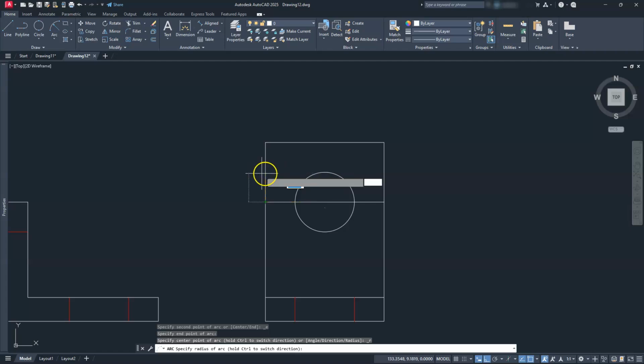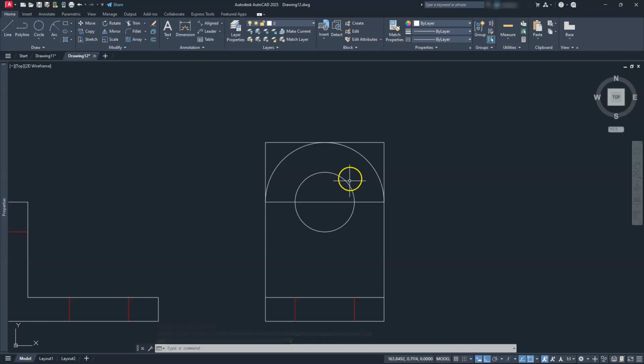Then what I like to do is try to give myself a preview of it showing up. Now I'll type in what the radius is, and we determined that that is 25. Go ahead and select that, and then you will see that you are able to get that radius. One of your last options here, if you just didn't want to do either one of those and you said, hey, I've got a nice fancy fillet command, go ahead and use the fillet command. So if I go to fillet, I can specify what the radius is. Remember, that is 25. Go ahead and hit enter.